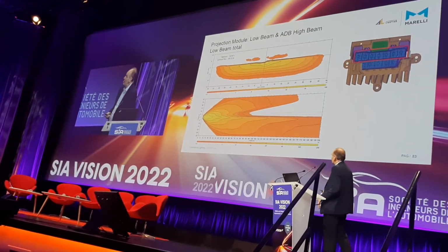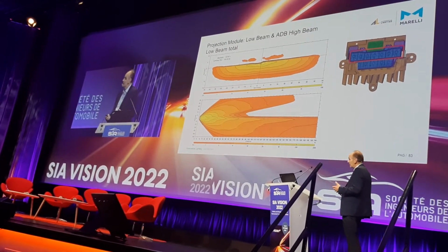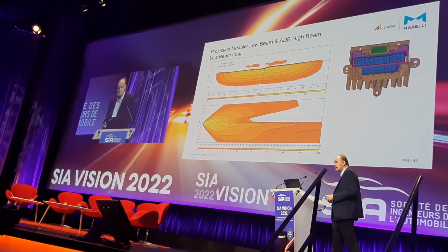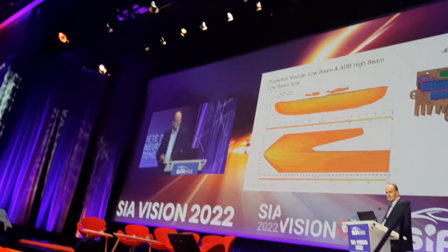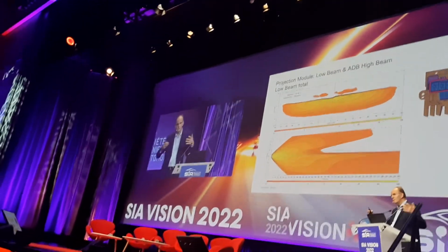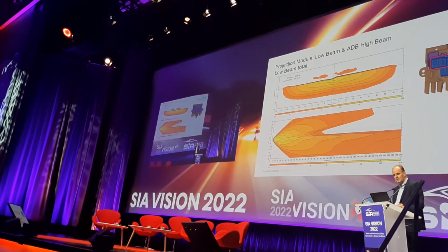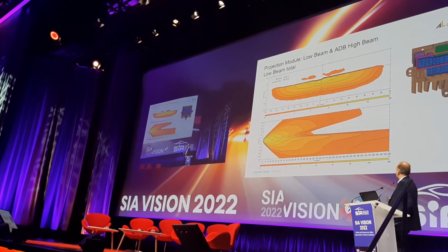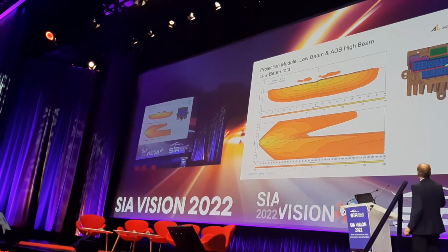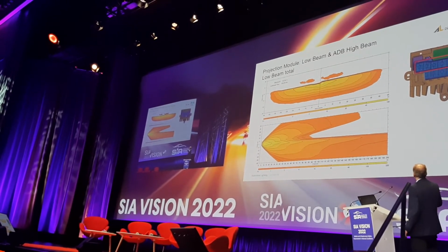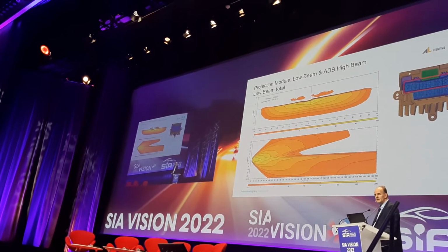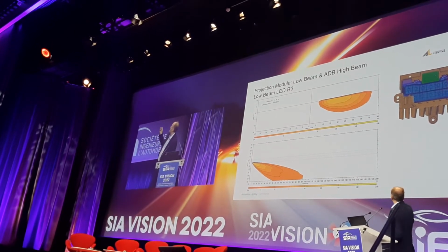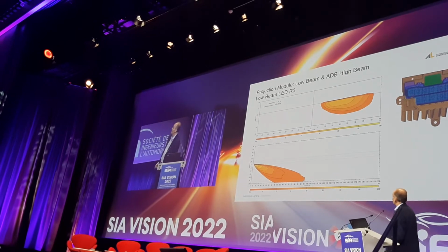And if we think about low beam systems which exist today on the road, we know such a system having 7 LEDs. We can play with the foreground, the side spread and the range area. I can demonstrate here: you see the light source with 7 LEDs for the low beam, the others are for the high beam, and when I switch on the simulation of each single LED, you see this is the first one on the right side, and this is side illumination.